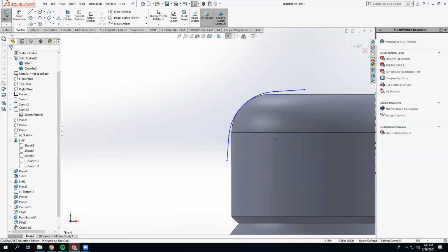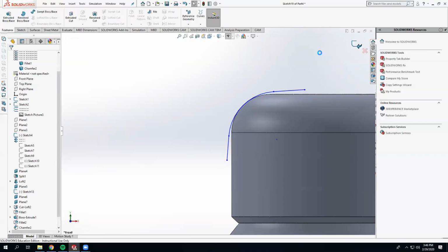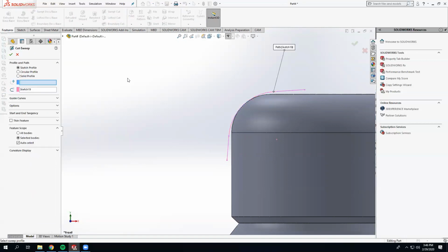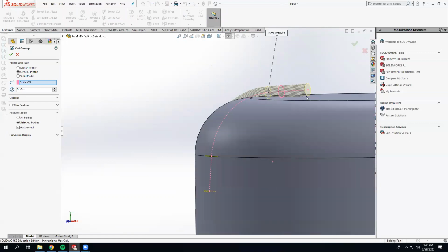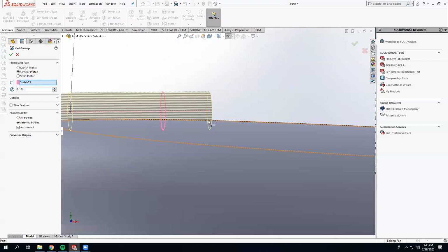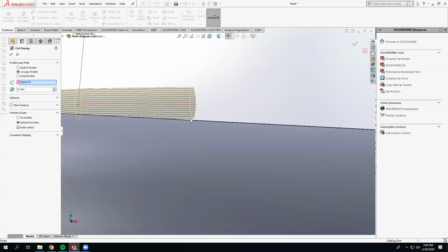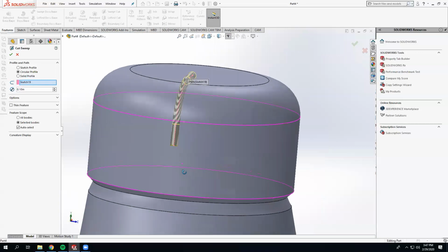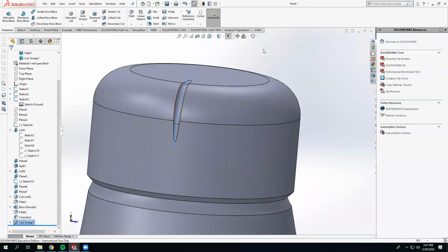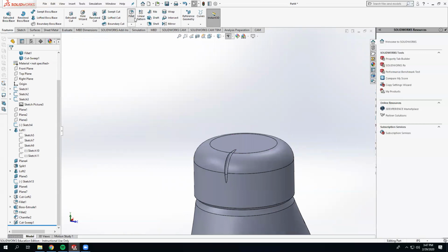Right? Then I'm gonna do features, and then I'm gonna exit this sweep cut. We've been using sweep where I need to sketch a profile, all of that stuff. But I think I showed you this circular profile, right? I talked about this at the beginning of the class. I'm gonna click here, and then automatically it gives me a circular profile, right? And I could look at the cut, and yeah, it is actually leaving. It's not touching there. It's touching the rest. That's good. Say okay, and I get that. Then I could add a fillet to that edge.